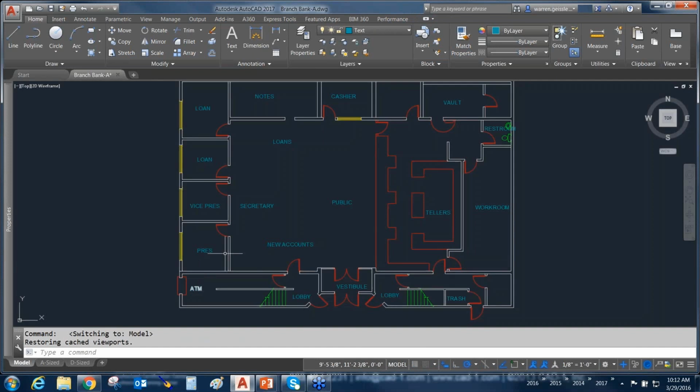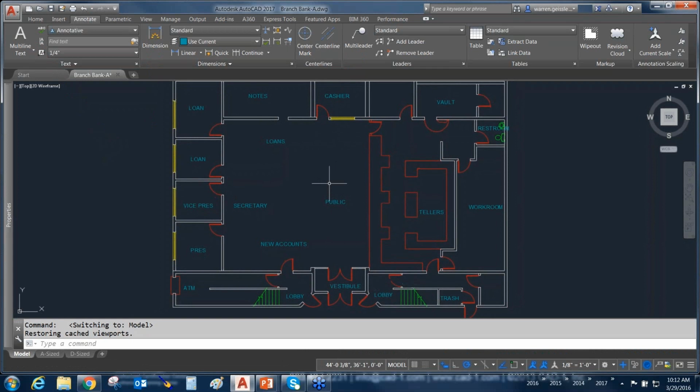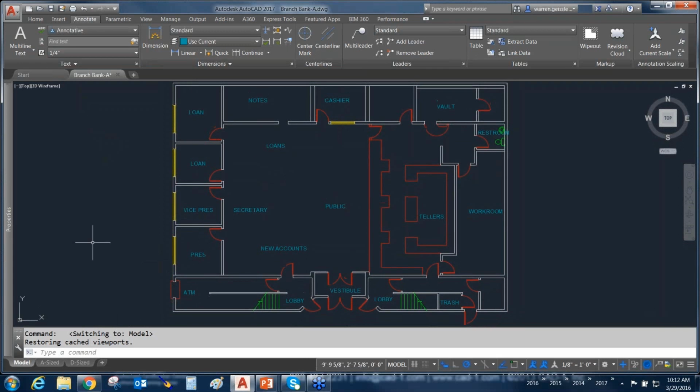Well, now, starting with AutoCAD 2008, we have got what's called annotative scaling for all of our annotation. And by all of our annotation, I mean what I'm showing you can be done for your multi-line text, single-line text, dimensions, multi-leaders, hatch patterns, and even blocks, so that when you insert a block, it'll automatically scale. Now, what does this do? What annotative scaling does is it allows me to put in one piece of text and have that text automatically set itself up as a printed height.